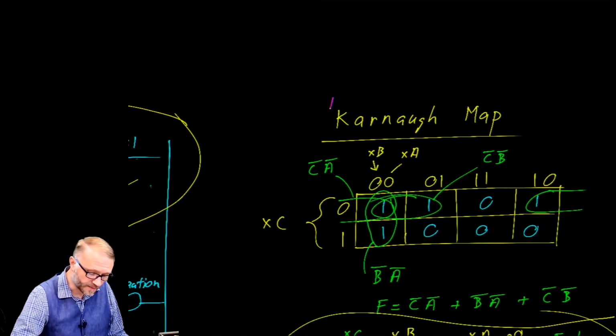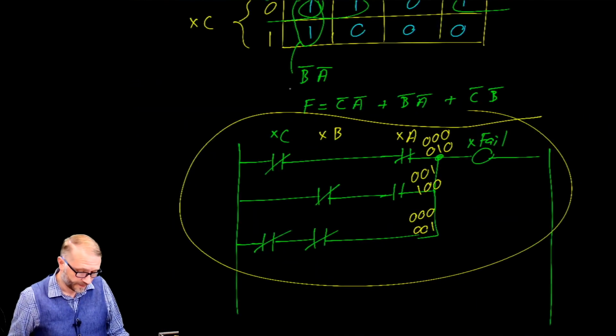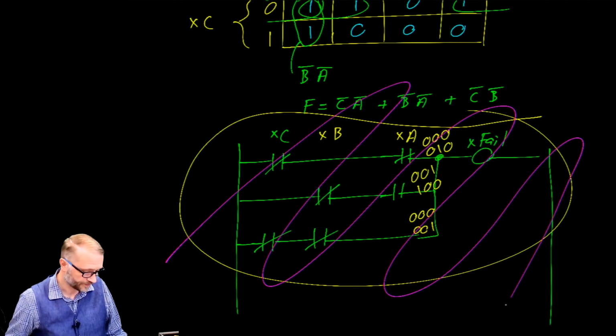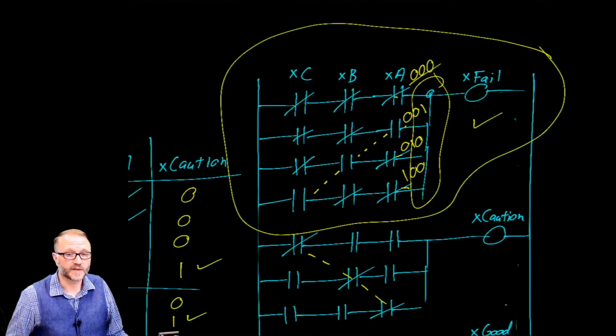We equated them using this Karnaugh map, which I didn't bother to give you any real directions on how it works. We said this circuit is considerably simpler. It has one less branch, and each branch has one less contact. However, all things considered, I would recommend against doing such a thing. From a memory perspective, there's no advantage whatsoever because the PLC has considerable memory. It's decimal dust to try to mess with this type of simplification.